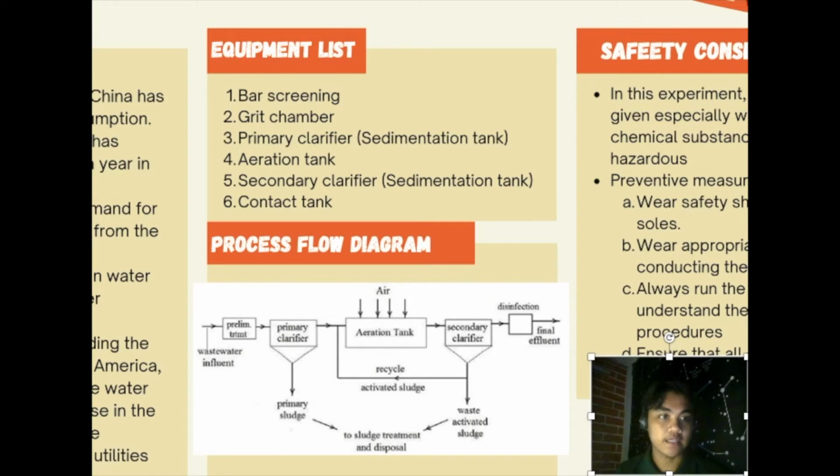In the aeration tank, the biological treatment of the wastewater occurs by pumping air to encourage the conversion of ammonia into nitrate and providing oxygen for the bacteria to continue to treat and stabilize the wastewater. After that, the treated wastewater flows from the aeration tank into a second sedimentation tank for further treatment of the wastewater.